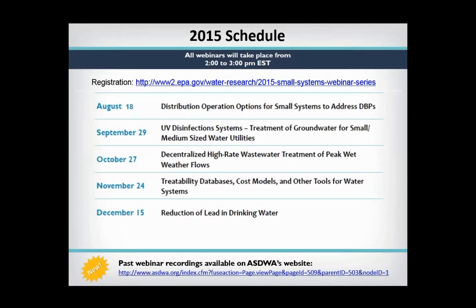Some media tend to like lower pHs, and that would be a caution. Depending on what your background DIC is, think about your new copper, whether the conditions are corrosive to new copper, and see if the combination of media and manganese removal would have any other adverse impacts on pH or alkalinity in the system.